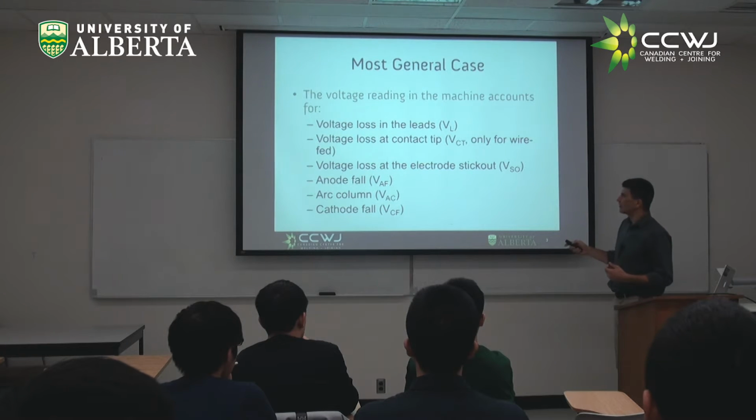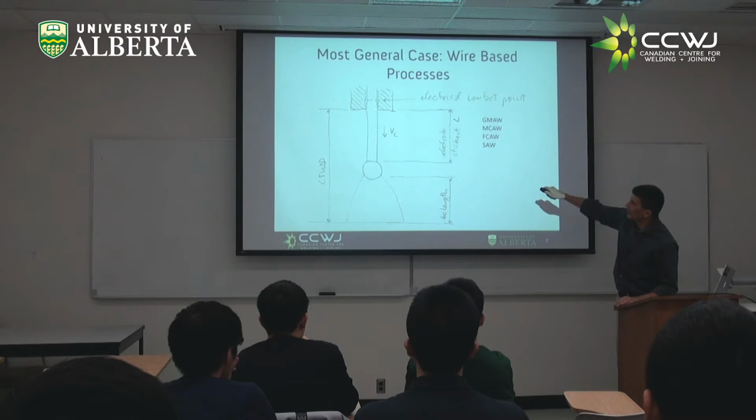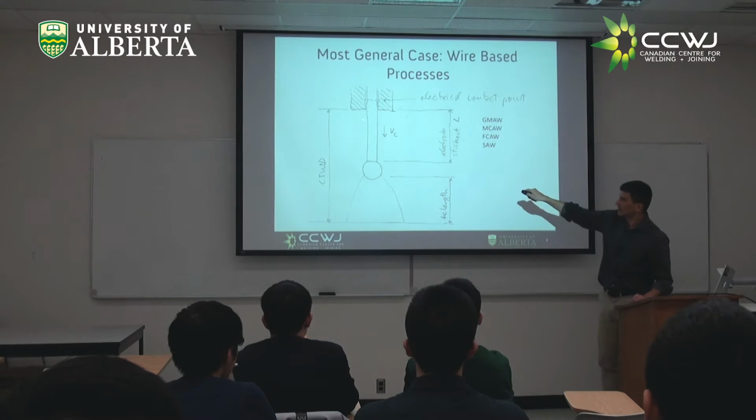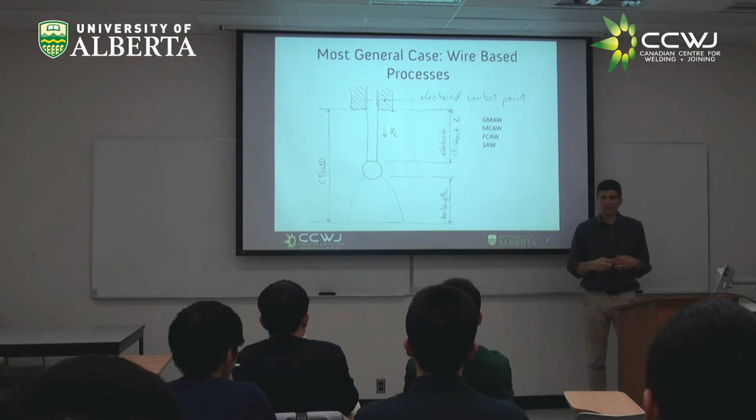And also, here, as the current is coming through the wire, we have also another voltage loss because of the resistance at the wire stick out. If I had seen MIG for the first time, I would have said, who cares?